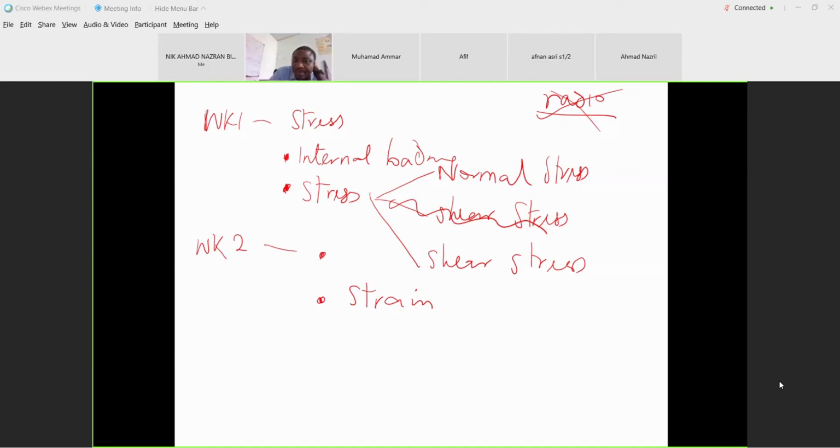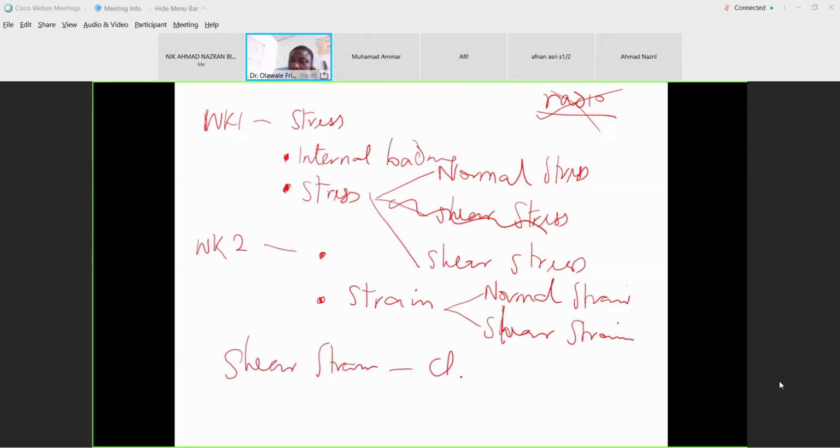Are you sure? Under strain, I looked at 2. I looked at normal strain, and I looked at shear strain. I covered everything in your last class. I covered all the lecture notes. I did one example on shear strain, and I asked you to try one other example. I remember saying in your last class that shear strain is change in angle. Your shear strain is gamma, which is your original angle minus your final angle. Most times your original angle is 90 degrees, which is pi over 2, because your shear strain is in radians, minus theta f in radians. And we solved one example in that class.